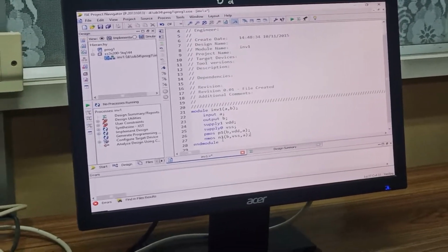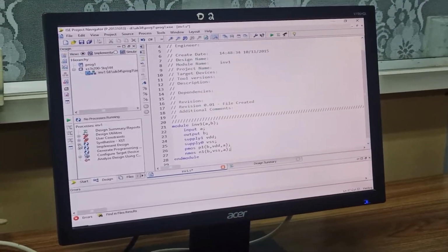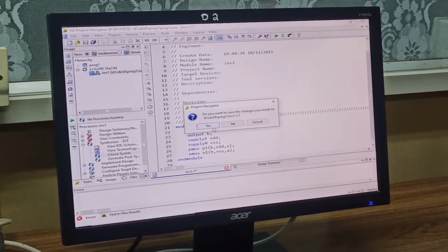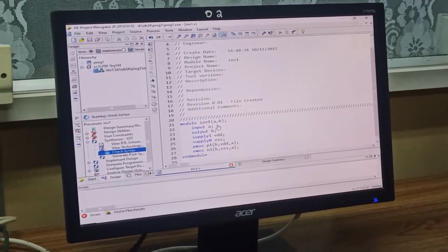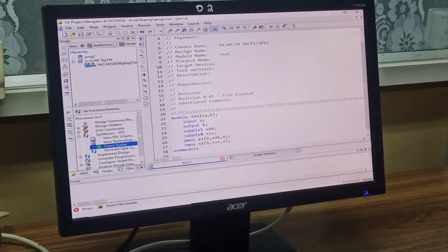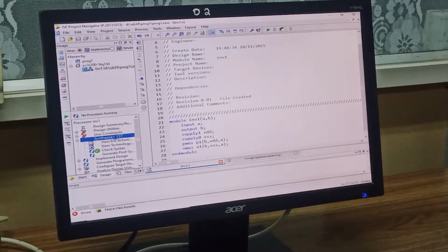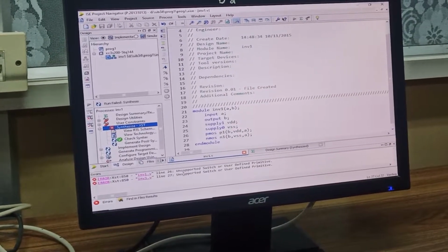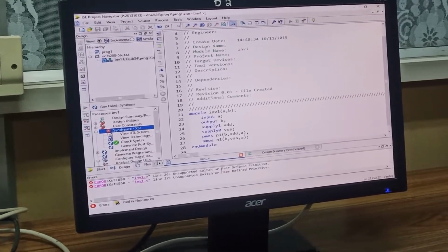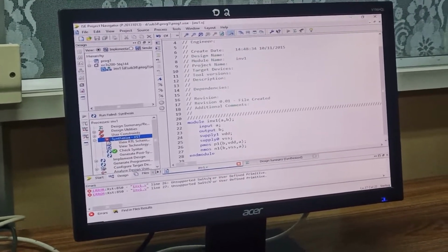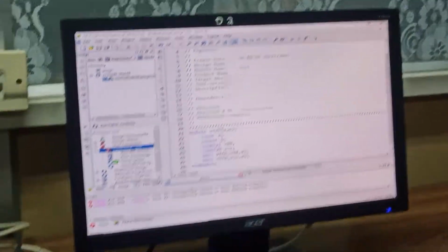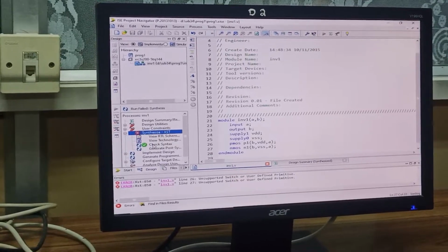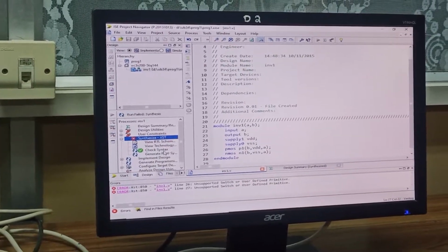We call this a Verilog code. This is switch level code. Check syntax here. Okay, it is corrected. It won't synthesize here. Even if I synthesize it, it won't synthesize because it is not included in the library. Switch level code is unsupported in Verilog synthesis. But it will check the syntax and it will generate the waveforms.